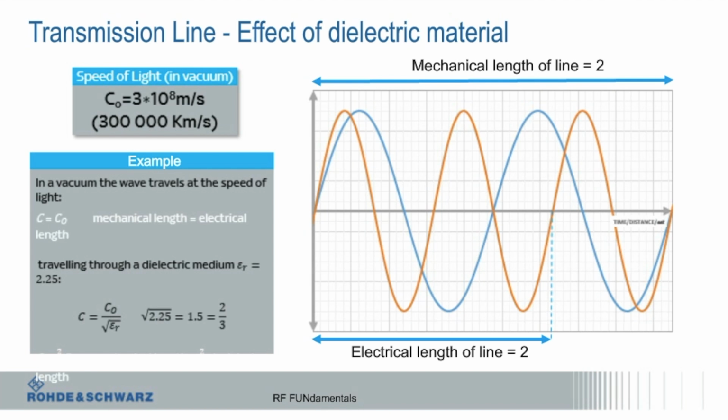But my point is more, you'll often see where somebody has an SMA cable from their whatever, and then they connect it to a BNC, and then the BNC connects to another BNC, which connects to an N, which goes to the instrument. Every interface there is degrading the standing wave ratio.